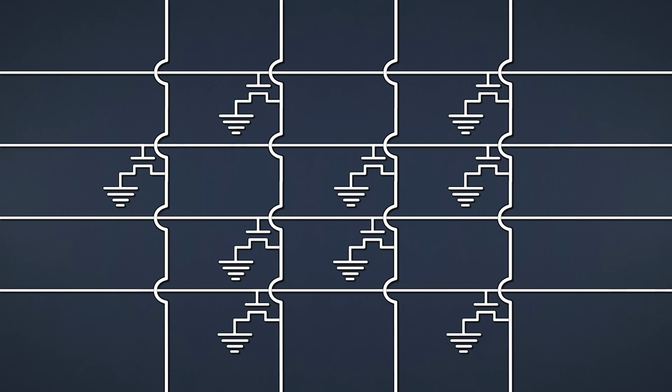First we set all bit lines to 1. Then we activate the word line. Now notice how the word line activates the transistor, which then redirects the flow of current from the bit line into ground. This turns those bit lines low, representing our zeros.